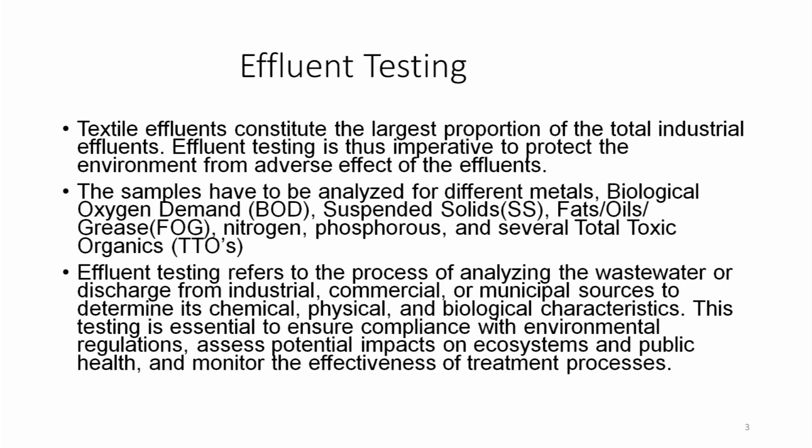So, unless and until we do a testing of influent and effluent and their characteristic of COD, BOD, TSS and other parameters like nitrogen, phosphorus and total toxic organics, total organic pollutants, we will not be able to know whether the technologies that we adapted for purification or remediation of textile effluents are working or not efficiently.